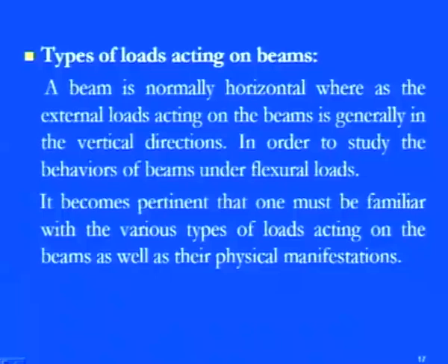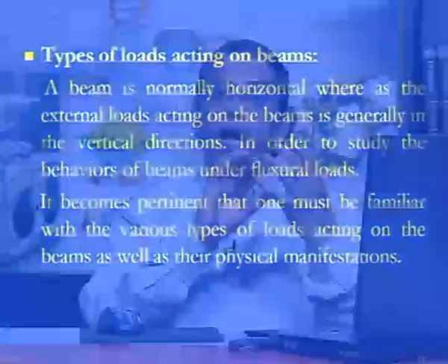It means this is the axis, and the loads have to act on the perpendicular axis, normal to this particular beam. It becomes pertinent that one must be familiar with the various types of loads acting on a particular beam, as well as their physical manifestation, that is, how they appear and what kind of deformation or stresses form due to them, the bending stresses or the shearing stresses. And since we know that bending stress is nothing but the combination of tensile as well as compressive stresses, we would like to classify beams on the basis of the types of load.